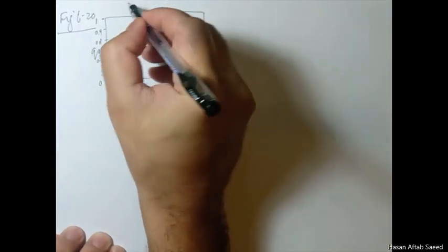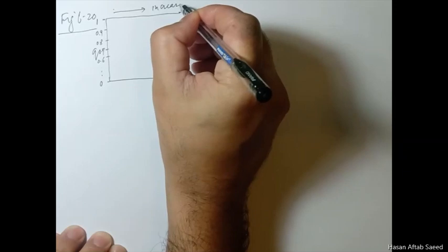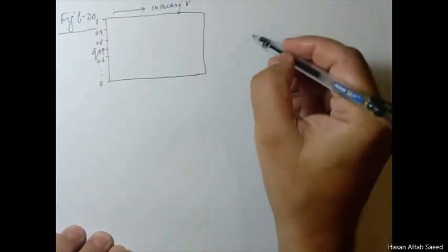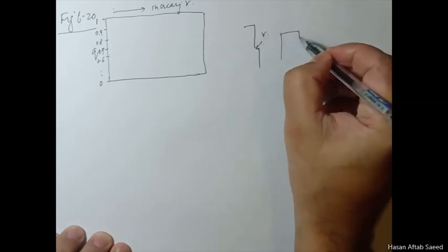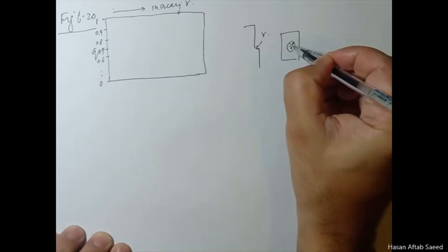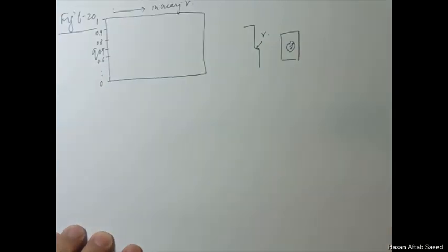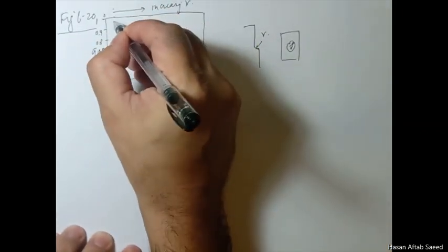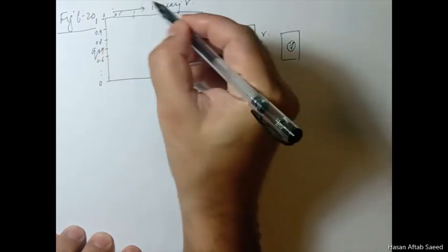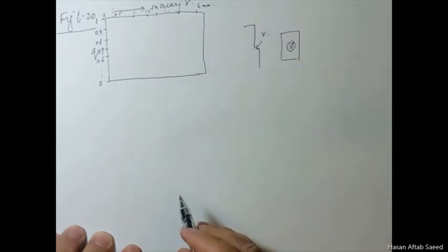On the x-axis you have increasing R. We are talking about radius, for example, change of section, this is R. In case of a hole, this is R. So in any situation, whatever fillet or radius is there, this is R. For example, this is 0, this is 0.5, this is 1, 1.5, and so on, and there you have 4 millimeters, for example.